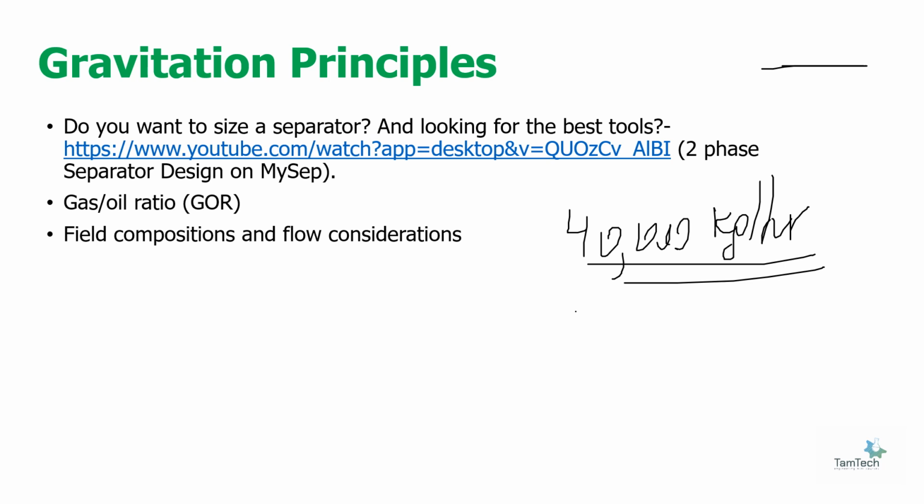It means that your separator must be designed for the full separation or the compositions that may be present during the life of the facility. It should be a very detailed design to perform this separation. This might include a change in the CO2 compositions, or H2S normally in the natural gas content, or how rich the gases are in natural gas liquids, or production water cut, etc. Whatever change you have in the compositions, your separator must be adequately designed for it.